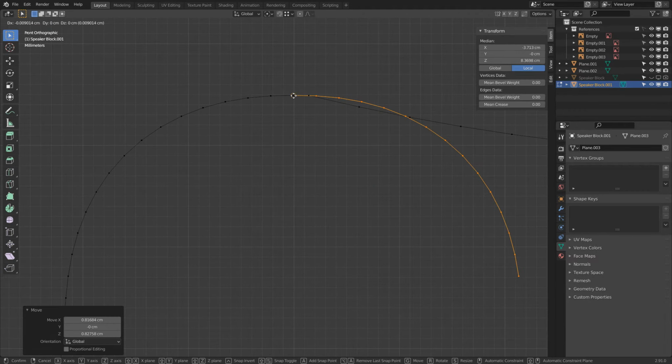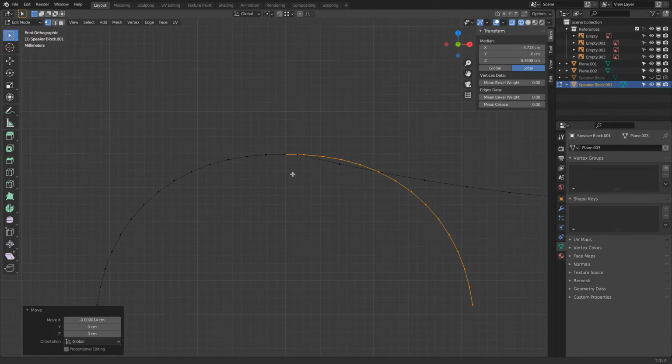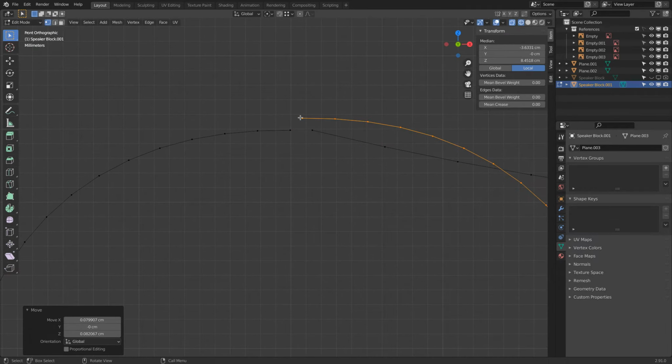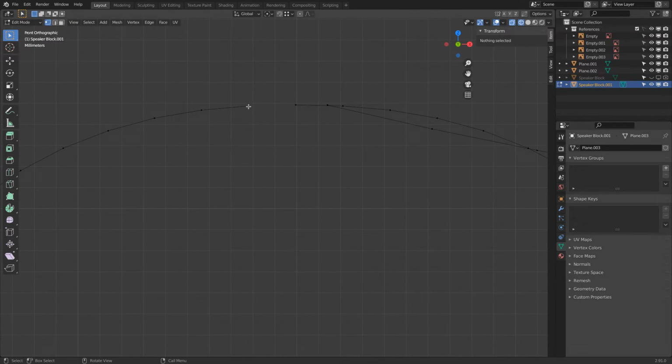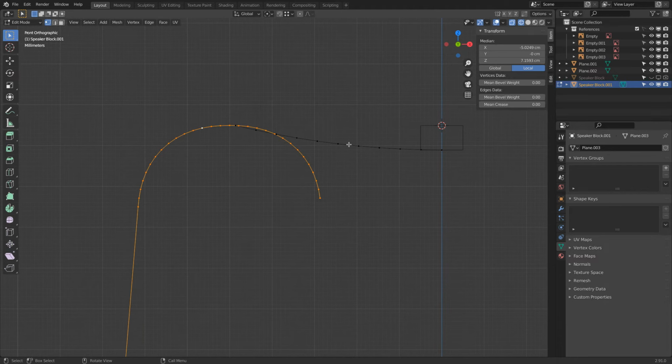Okay, G, hold control. Now there we can see, so this comes up, and then this goes down. Okay, yeah. Let's do the following. I move this one to here, G, hold control. Perfectly, that snaps. This point I move to here, press X and delete, select these 2 points and fill the missing element in. So now you see this is one big piece. Cool. Okay.